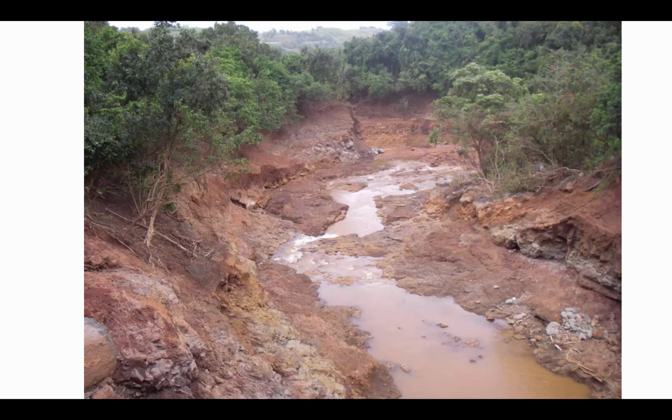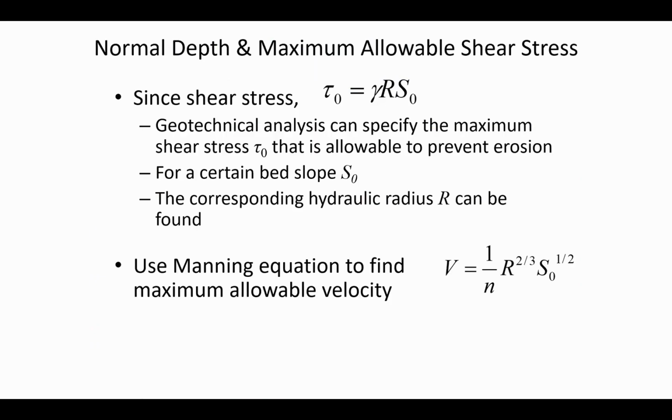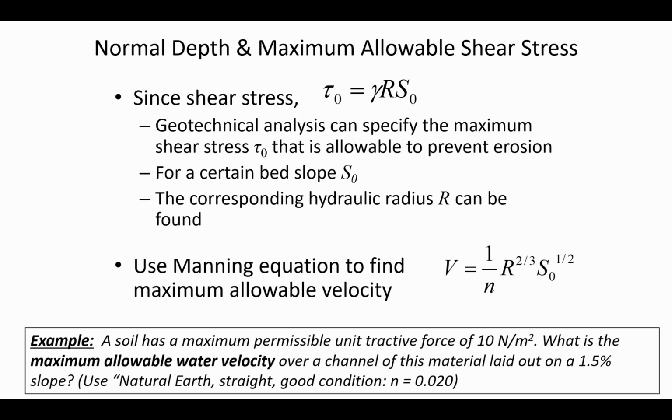But when it's relatively dry weather, or if it's wet but not flashy, if it's just a steady rain and it's not scouring the channels quite as much, then the water doesn't look that chocolate brown color that you'd associate with scour. So just to get some practice with this idea of permissible tractive force, which is related to the shear stress that you can apply to a natural surface and not induce scour.